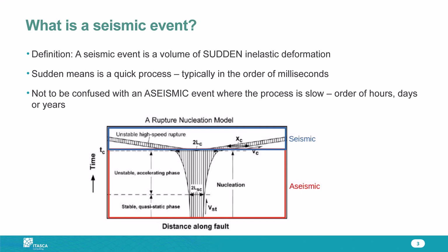And in our numerical models, it's exactly the same. The majority of the plasticity in our numerical models is aseismic, not seismic. So often when we write reports or we look at reports from consultants, they try to calibrate their numerical models with seismicity, and they even use parameters such as plastic energy and compare that to the seismicity. And often they overestimate how much seismicity the model actually produces, and this is why. It's because the majority of that plasticity is aseismic.